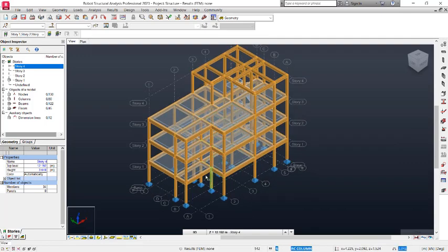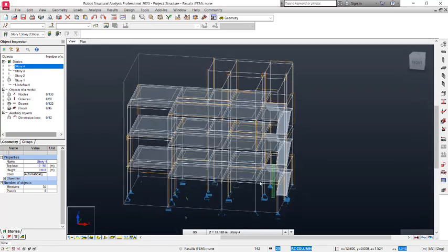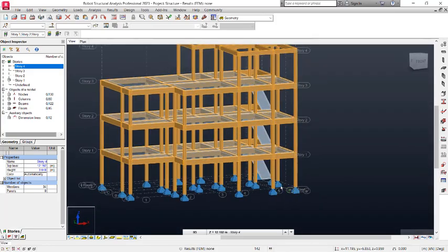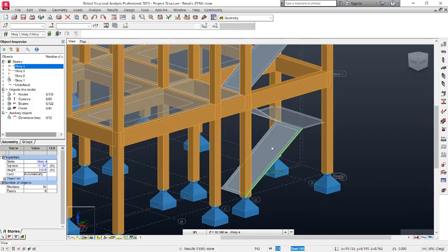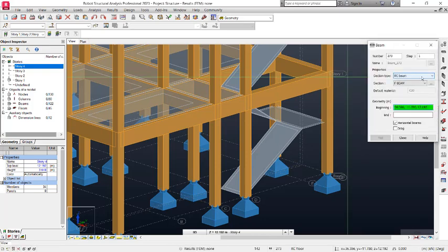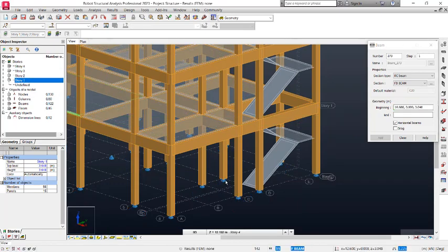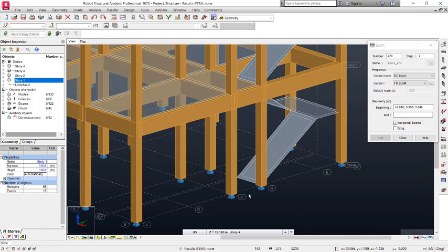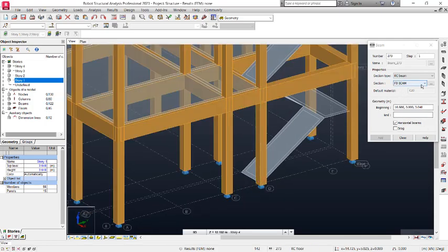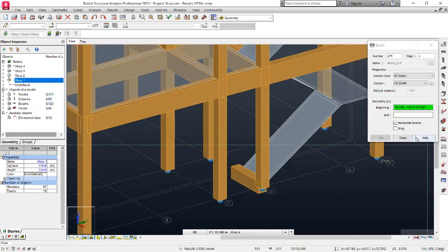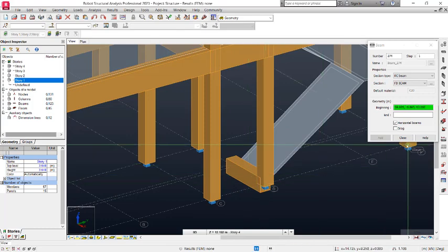Okay, so for us now to work on the foundations, we need to place the foundation beam right here to support this entry stair. Okay, so what we need to do is click on the beam options right there, and then we have beams right there, FD, which is foundation beam. So we are placing it from, so let's navigate to the story 1 right there. Okay, this story now we pick this point all the way to that point, to place that beam successfully.